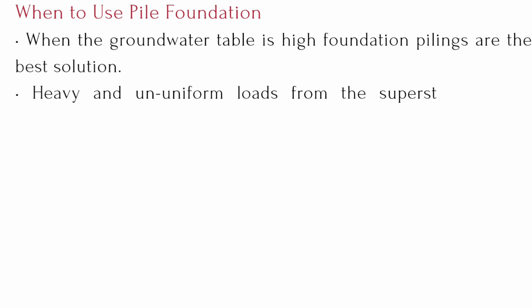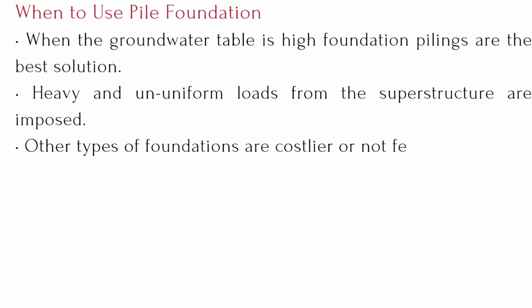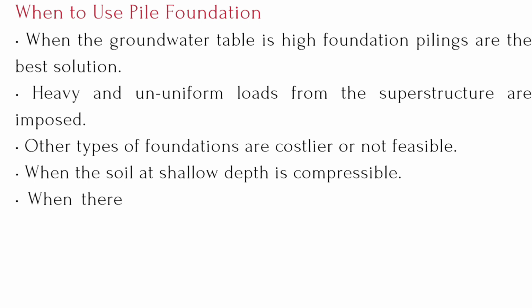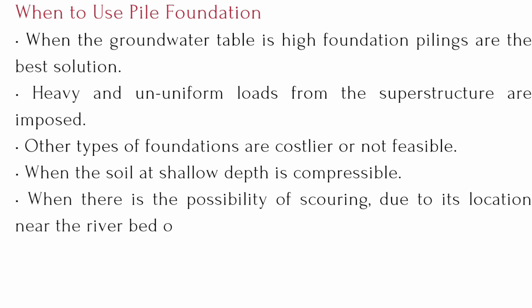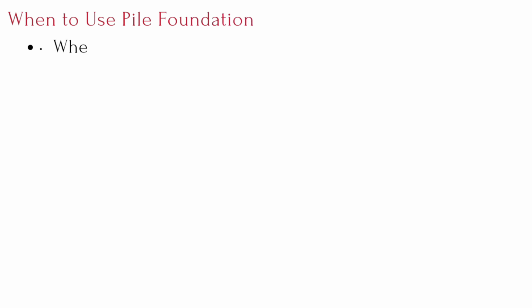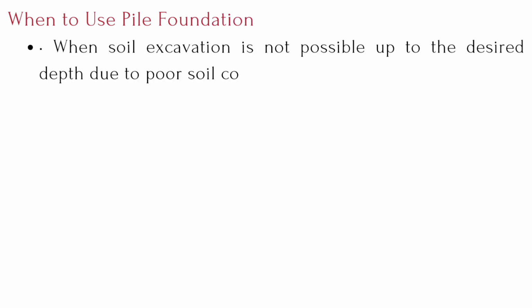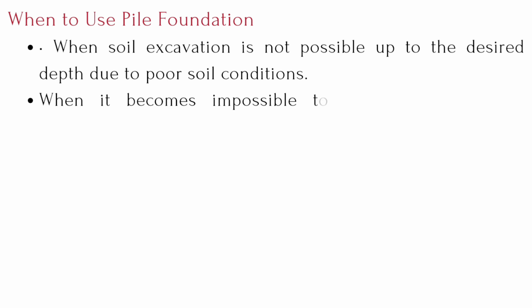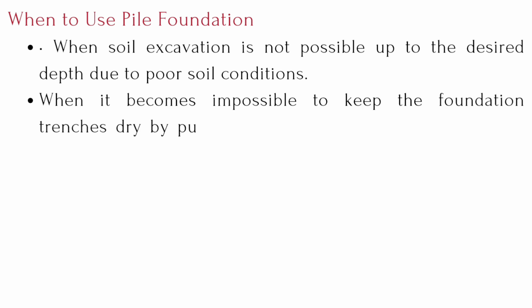Pile foundations are deep foundations. They are formed by long, slender, columnar elements typically made from steel or reinforced concrete or sometimes timber. A foundation is described as piled when its depth is more than 3 times its breadth. Foundation piles are usually used for large structures and in situations where the soil at shallow depth is not suitable to resist excessive settlement, resist uplift, etc.